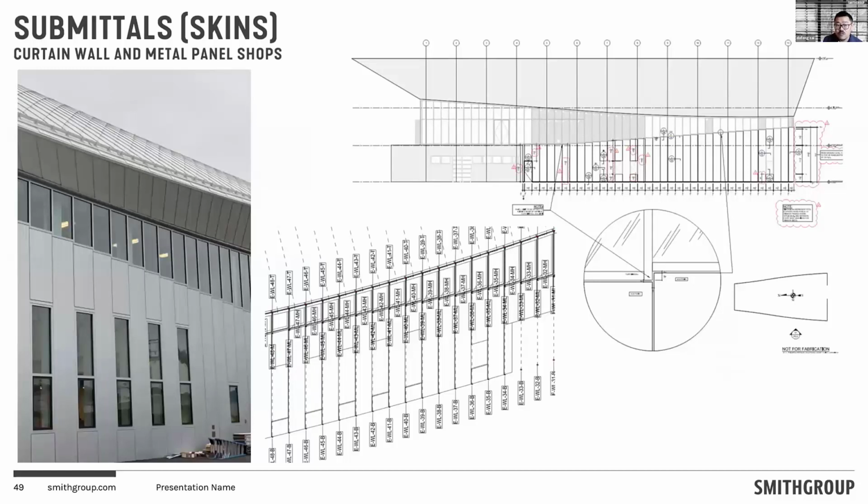For example, for this project, we have the seal of the curtain wall continue stepping down to form the curve along the building facade. And then you need to think about how the reveal of the metal panel cannot be aligned with the center of the curtain wall. Otherwise, people cannot construct it. So you have to make sure all those reveals align with one side of the molding so you can make every detail constructible.